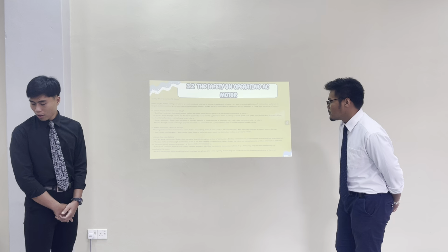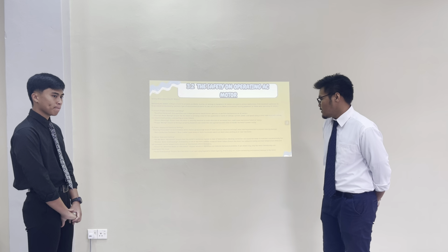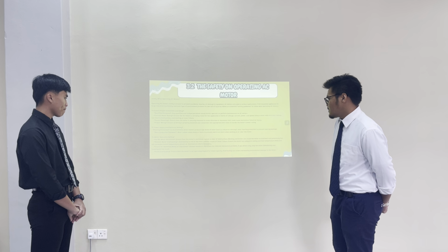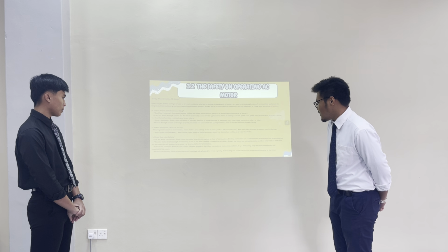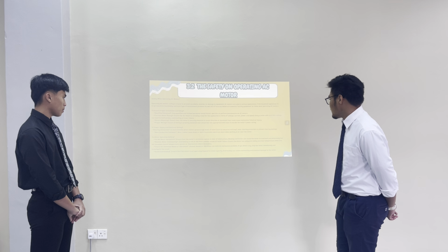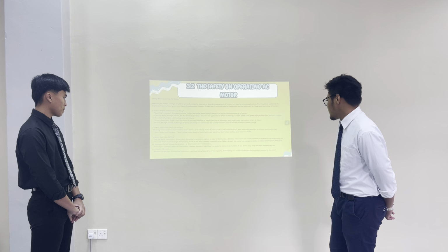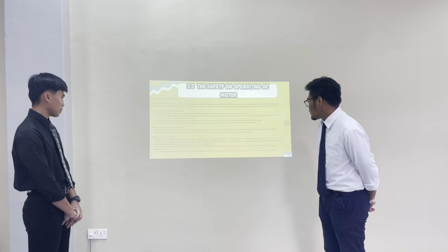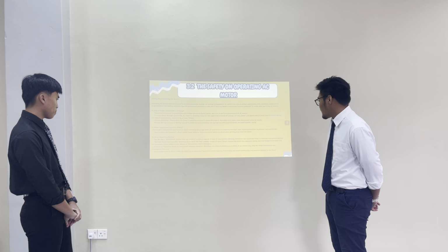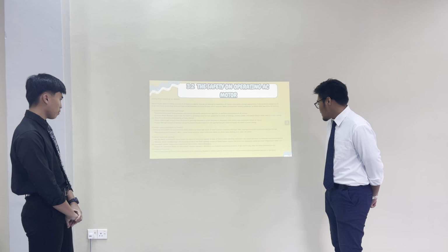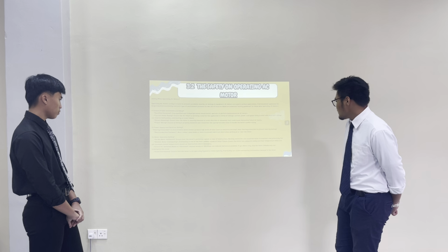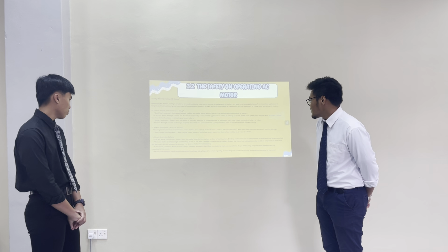Number 4, motor operating safety. Do not block ventilation. Ensure that the motor's ventilation system is clear of obstruction. Blocking ventilation can cause the motor to overheat and potentially fail. Monitor motor overheating. Overheating is one of the most common causes of motor failure. Ensure the motor has adequate cooling and that temperature limits are not exceeded.